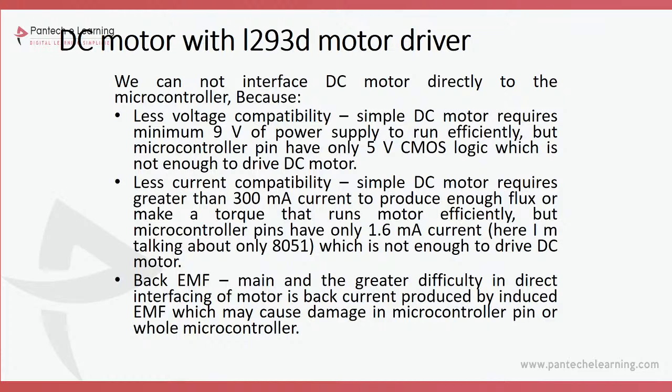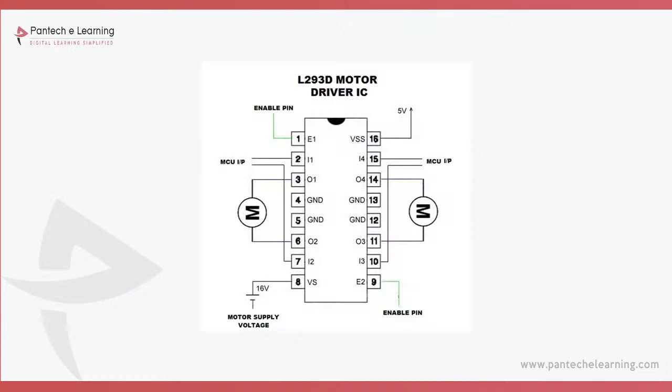And a DC motor with L293D driver. It is known to everyone. That is nothing but an H-bridge motor driver which has the capability of connecting two motors. We provide the input pins, and there will be 4 pins from the Arduino, and those 4 pins indicate the direction of the motors. So 2 pins equal the function of a single motor only. In that ratio we will be connecting the pins.